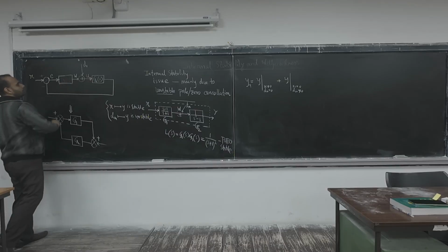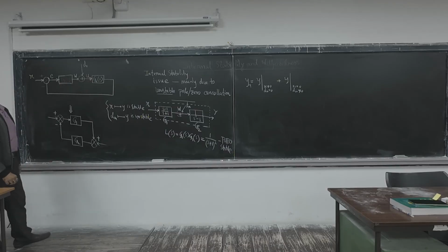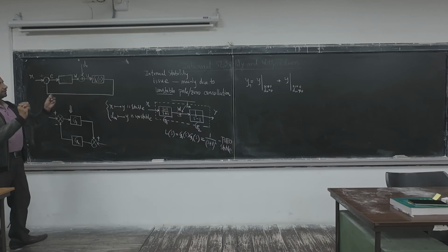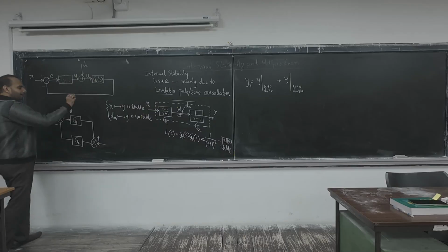So if we think only about BIBO stability, then in controller design, if there is an unstable pole-zero cancellation, internally there is a big problem, but we are not taking care of that. That's why there is the internal stability concept. Asymptotic stability is a mode that gives more insight than BIBO stability. I hope all of you will agree with that.